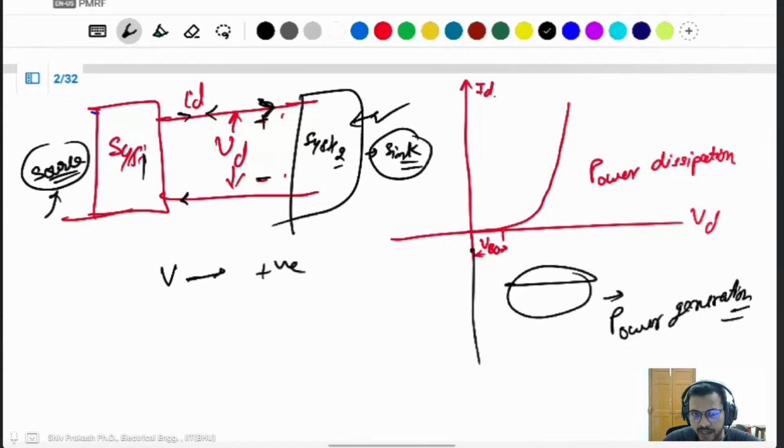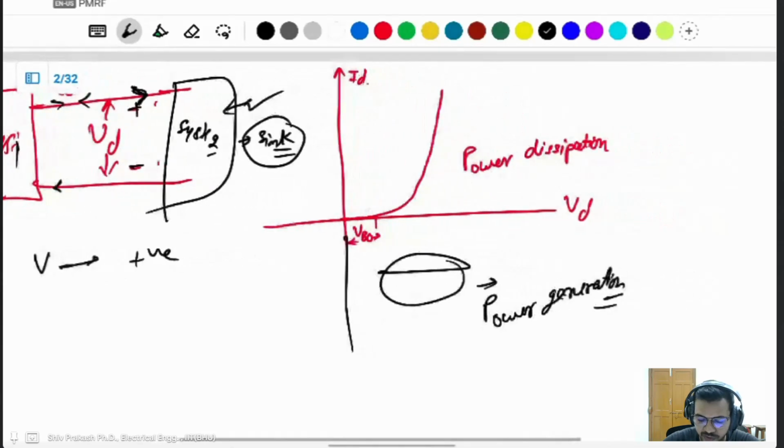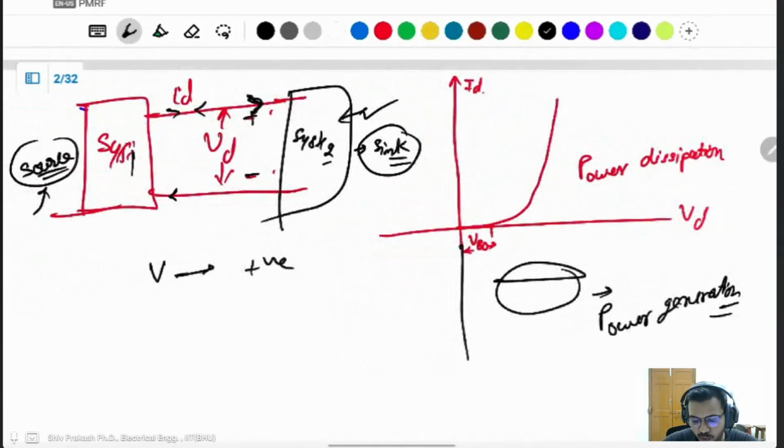In a simple diode characteristic, if you give some voltage across it, it will block until it reaches the cutoff voltage. After that, current flows through it, but it is non-linear in nature, not linear like a resistor, inductor, or capacitor.